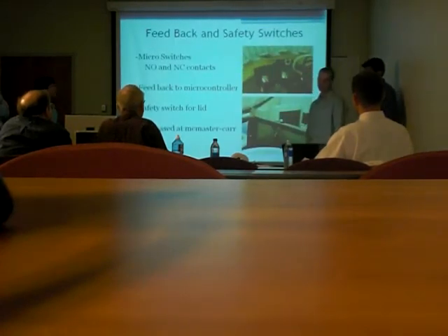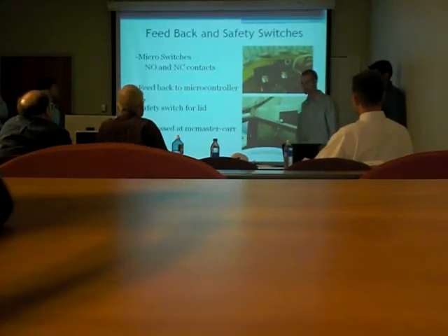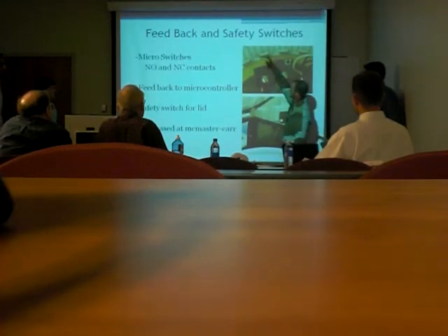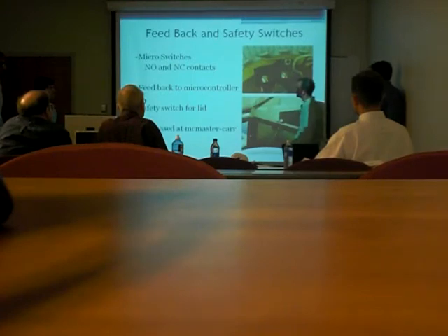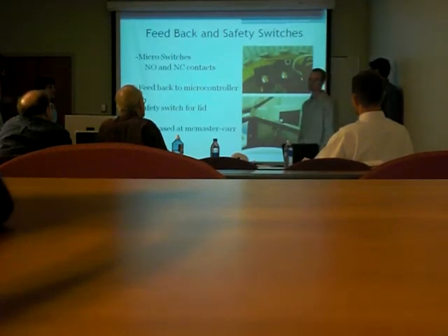I use micro switches for feedback control and also for safety switches. For the feedback control, it's kind of hard to see, there are tabs that are lined up with the hole slots, and every time that it moves, it will click the switch, and it sends feedback to the microcontroller telling it to stop the motor because the holes have lined up. And so that's how we know every single time that it's going to line up that the pills are being dispensed.